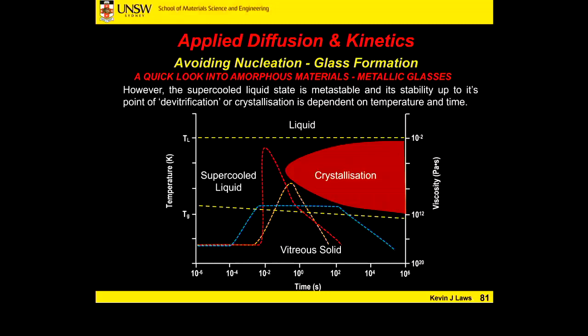So you know you've hit the crystallization hump if you've got tears or clumps? Yeah, so two things. You might be exceeding the flow rate of the material, which is a viscosity-based phenomenon. Or you're changing the flow rate of the material by inducing these particles, which creates localized shear around the particle. Localized shear leads to tearing. Or you can observe it experimentally. You can do differential scanning calorimetry. You can see when the crystals start because there's an energy signal transferring from the vitreous solid to a crystalline state. It's an exothermic reaction.